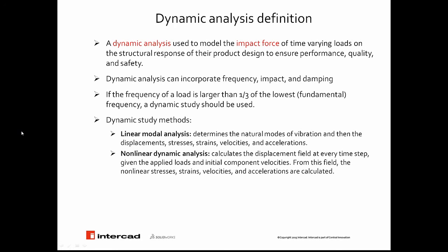One is linear modal analysis, which determines the natural modes of vibration, and then displacement, stress, strain, velocities, and acceleration are computed. And in the nonlinear dynamic analysis, we are calculating the displacement field at every time step, given the applied loads and initial component velocity. What we get from this field is the nonlinear stresses, strains, velocities, and accelerations.